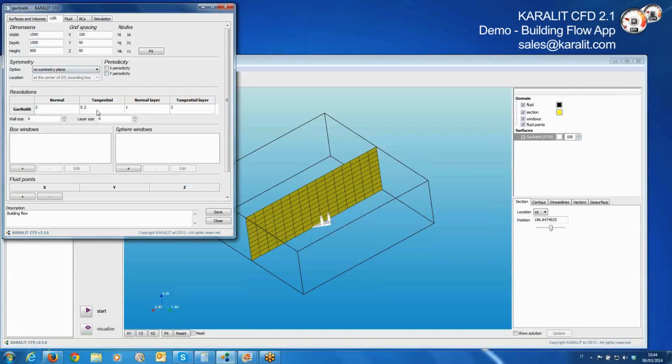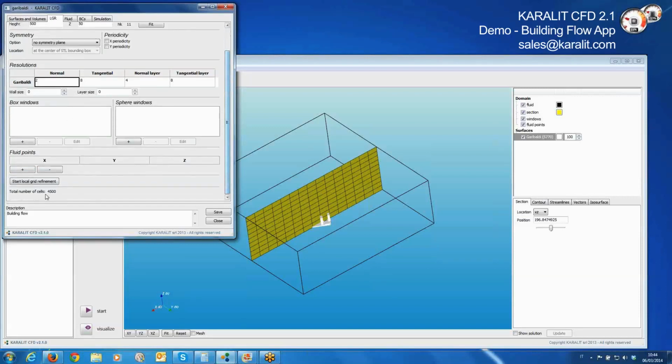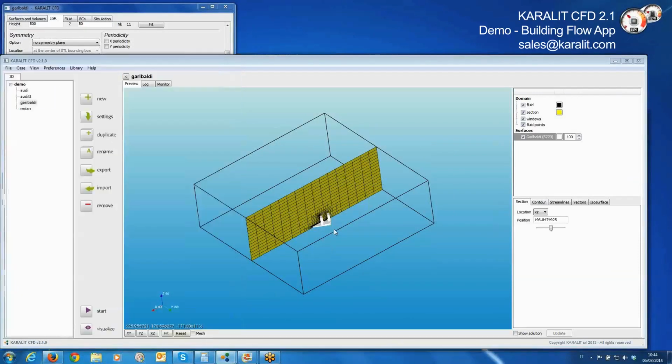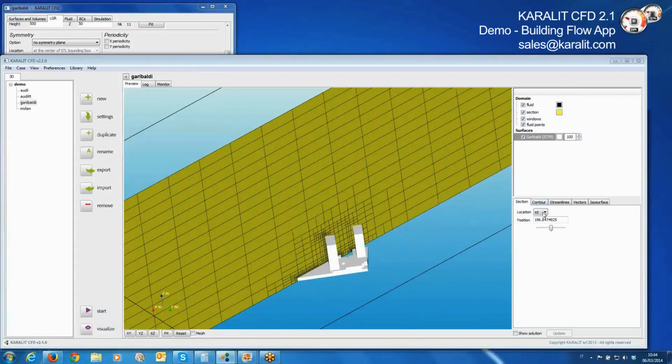Then we can use, for example, resolution of the wall with a resolution in the outer layer. So the initial grid spacing will be refined up to the wall by choosing these parameters at 2 meters, 4 meters tangential. We can also increase in order to give a proper aspect ratio to the cell near the boundary. And basically, those will be the basic step that will allow us to generate a first tentative mesh.